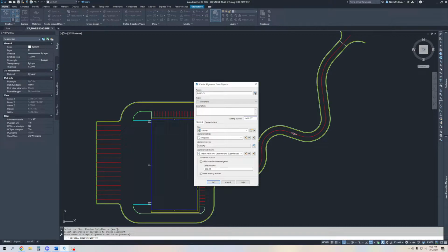If you had 1 plus 00, that's going to be 100 feet. And so on. The more zeros you add, the more it's going to be. 10 plus 00 is going to be 1,000 feet. 100 plus 00 is going to be 10,000 feet, whatever it may be.